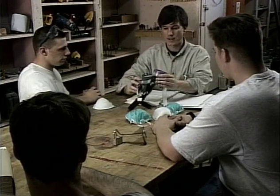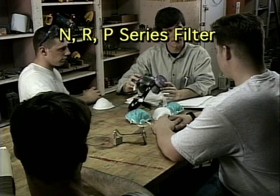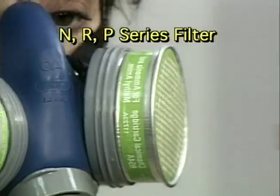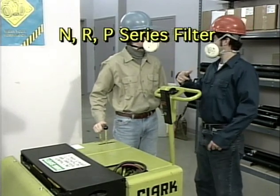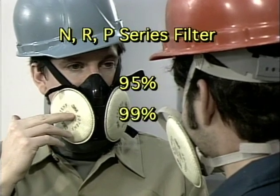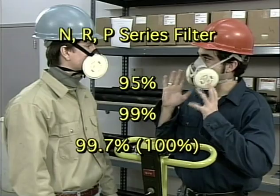Once your employer has determined whether you should use an N, R, or P series filter, you will need to make sure that the filter you select is also strong enough to block the airborne hazards you are working around. The strength of a filter, also referred to as its efficiency, is listed in percentages, such as 95, 99, and 99.7%, which is referred to as 100%. These are printed on the filter labels immediately following the N, R, and P designations.